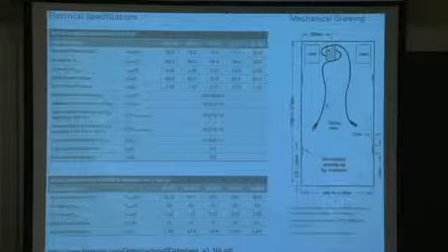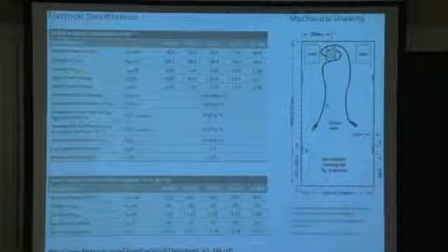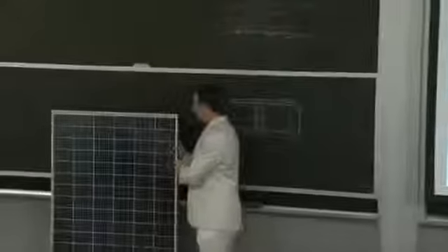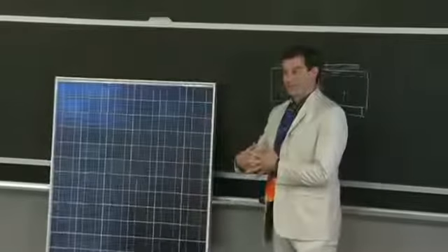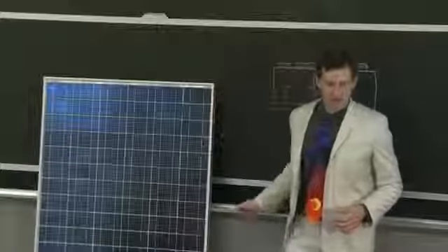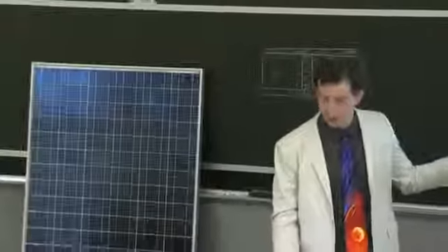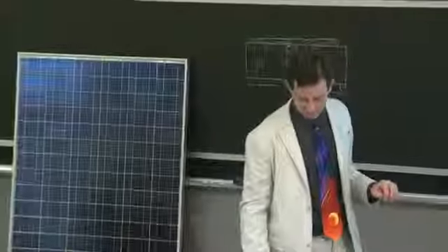One thing to note right here is that on the back sides of your modules, you typically have a little diagram that shows you how to interconnect one module to the next. And those are the cables that are used to do the interconnection. There are some companies trying to get fancy right now and saying, well, instead of interconnecting and then affixing the modules separately, why don't we just make modules that kind of click together? Part of the clicking process is the electrical interconnection, and the other part, obviously, is the mechanical rigidity. So there's certainly room for optimization on module design.